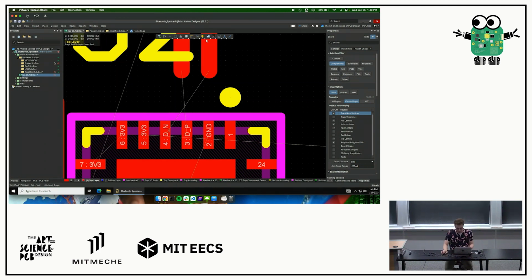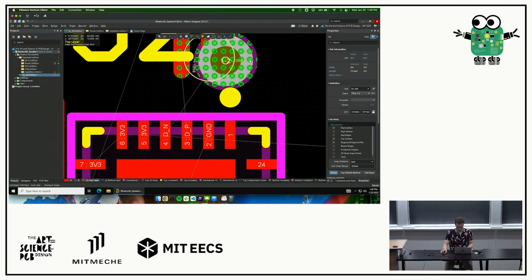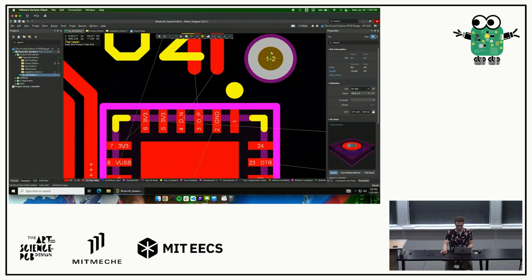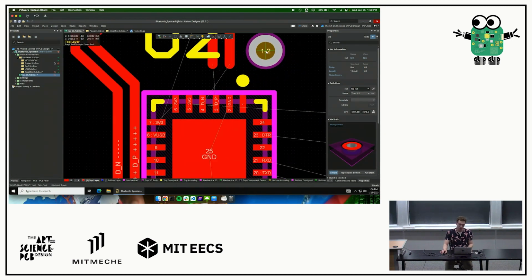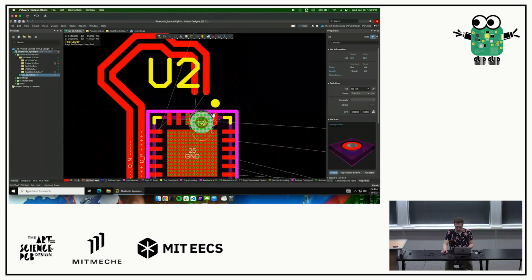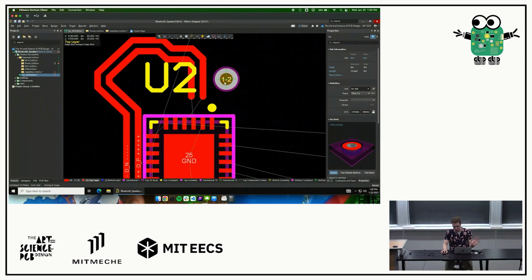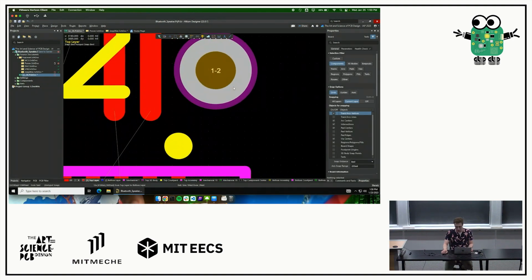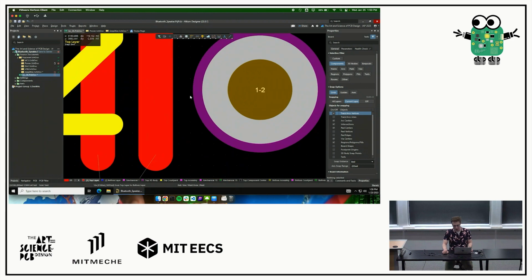And so you can do that by just adding a via. The button for that is up here. You can click Place Via. And then it's actually, vias by default are a little bit large. You can make them smaller, but it's more expensive too, so we'll just go with the Altium default. And then we can make this via carry whatever signal we want.